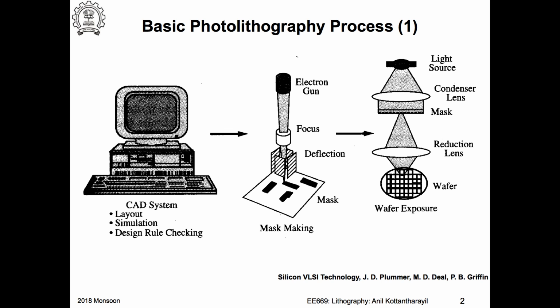Resist is very simple. It is a fairly high viscosity liquid, like good quality honey. You drop this on the center of the plate, and then you spin the plate at very high speeds, 10,000 RPM and so on, typical numbers. I spin this very fast, so it spreads. The photoresist, or in this case electron beam resist, would spread on the wafer.